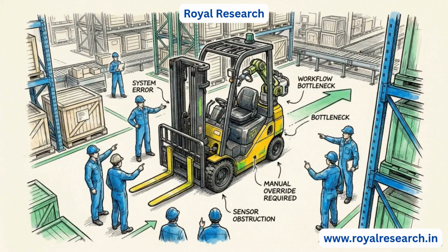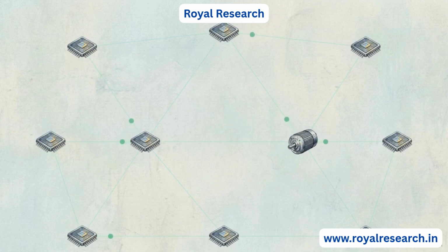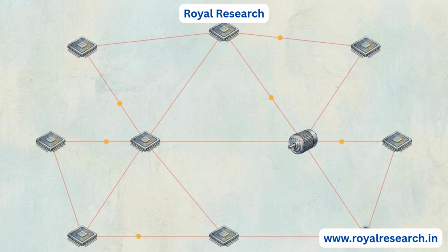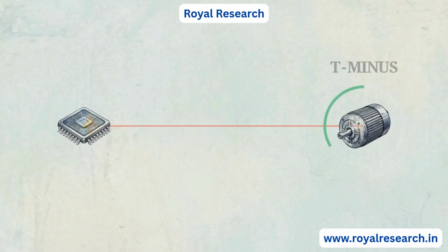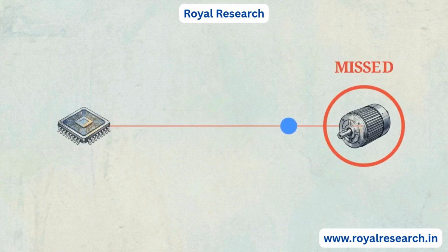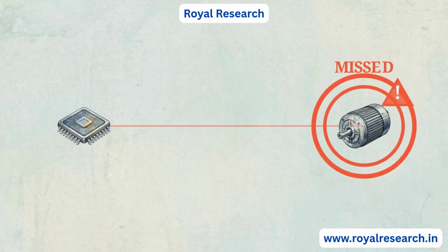Moving these decentralized systems into real-world production reveals the limitations of the original framework. ROS1's primary vulnerability was an inability to guarantee strict real-time execution. In complex environments, it struggled with data packet latency. Deterministic performance is essential for safety. If a self-driving car reacts to a hazard, a delayed command can lead to system failure.